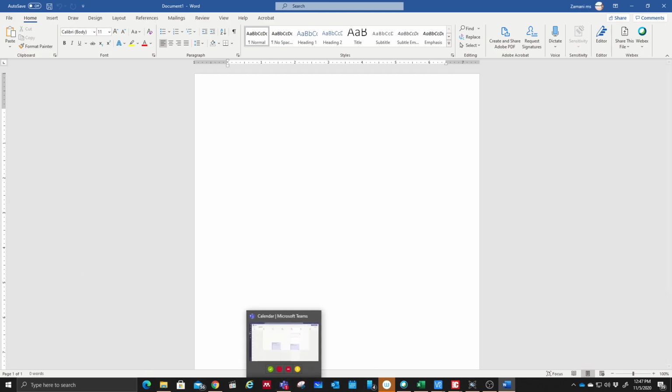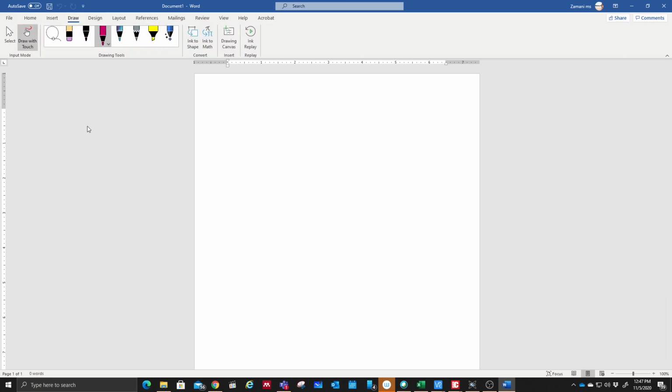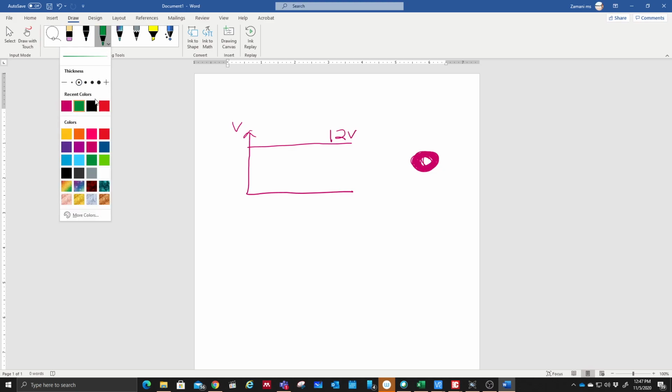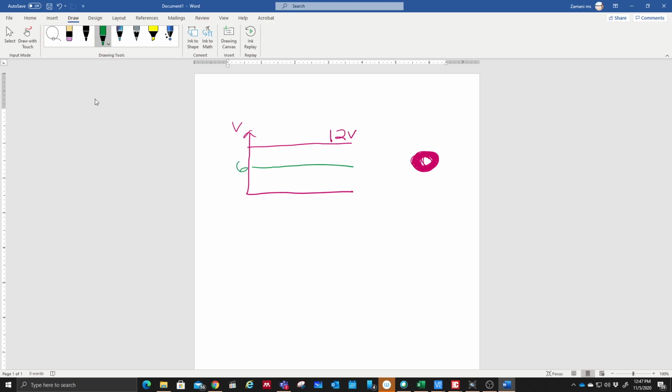Here is the battery voltage, right? You can see, okay, hold on. This is a graph, right? This is the voltage. You give 5 volt here all the time, so it means the rotation is good. This is, for example, 12 volt. The rotation is always like this, right? This is the rotation. If you give another value, maybe half of it, around 6 volt here, the rotation will be a bit slower, half of the full speed. So this is a direct one.